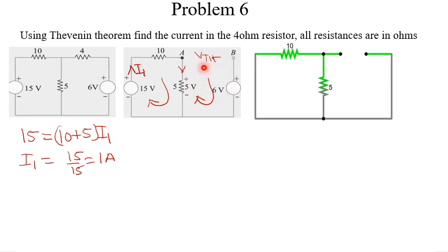So here in the clockwise direction, we meet the voltage source. The first voltage source is VTH, so we have VTH here. Then from this 6, we are moving from a higher potential to a lower potential, so it becomes -6.